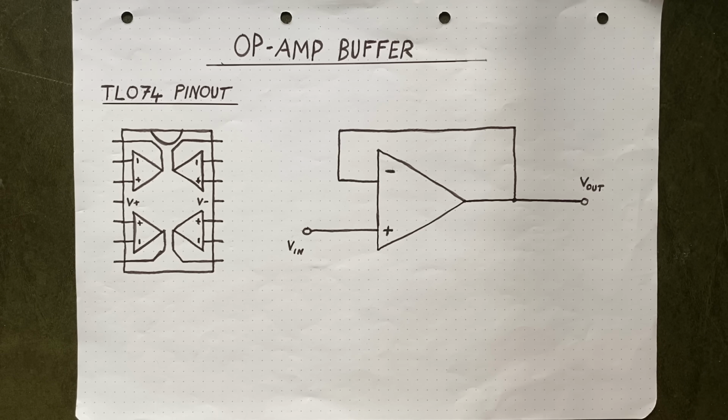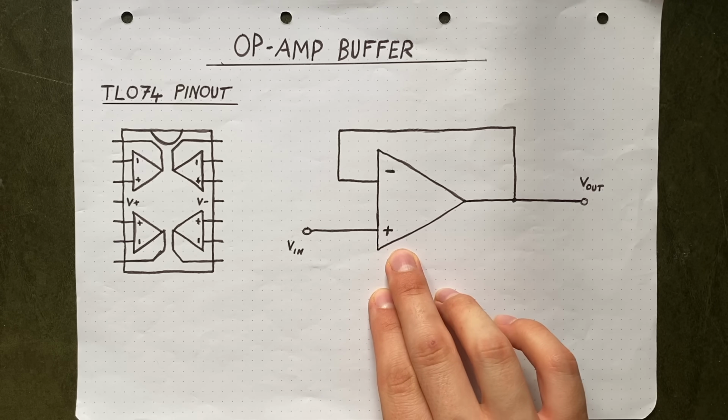And since no current is flowing into the sensors, they are not interfering with what they're attached to. That's why they are a perfect fit for our problem here. With a buffer, we can leave our oscillator structurally intact and working, while still being able to listen in with our sound system. To build a buffer, I'm going to use an op-amp, set up like this.